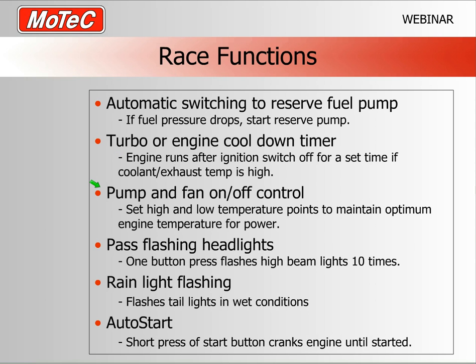Another simple output function which is made a lot more flexible with a PDM is normal pump and fan control. Now typically engine cooling fans just have thermostats or other such temperature sets. If you have a PDM, you can set both the high and low temperature points for your fans, or perhaps if you use an electric coolant pump, the same thing could apply to that.